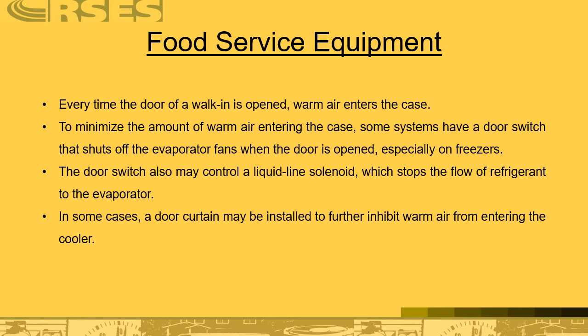Every time the door of the walk-in is open, warm air enters the case. To minimize the amount of warm air entering the case, some systems have a door switch that shuts off the evaporator fan when the door is open, especially for freezers. The door switch may also control the liquid line solenoid, which stops the flow of refrigerant to the evaporator. In some cases, a door curtain may be installed to further inhibit warm air from entering the cooler.